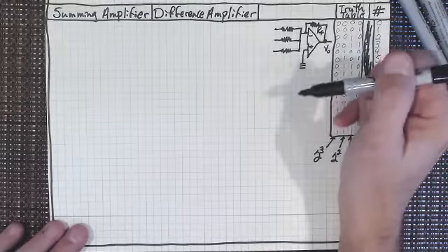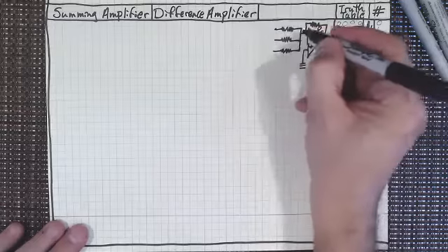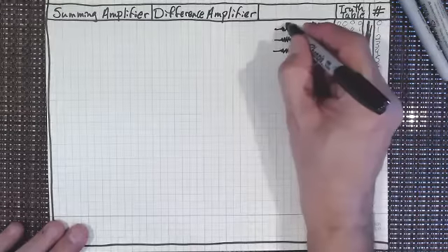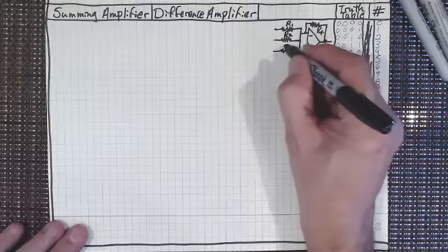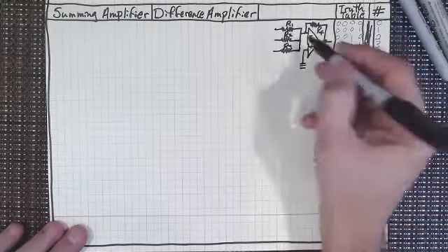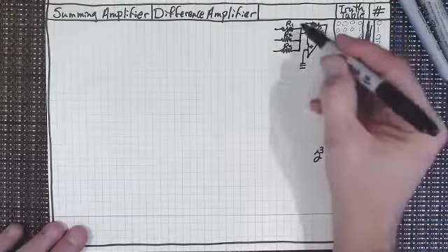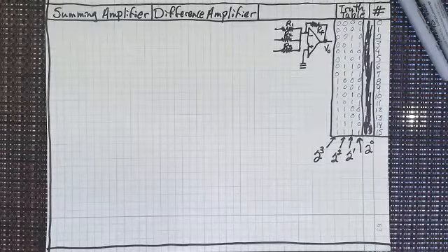With the summing amplifier, it's just like an inverting amplifier, right? So I'm just drawing it, just like an inverting amplifier. There's my output, V out. I'm also going to have a feedback resistor, there's my feedback resistor, R sub F. And then I also have resistors here. Now, these resistors do not have to be the same value. So I'm going to call them R1, R2, and R3. I'm going to stick as much to the notation in your textbook as I possibly can.